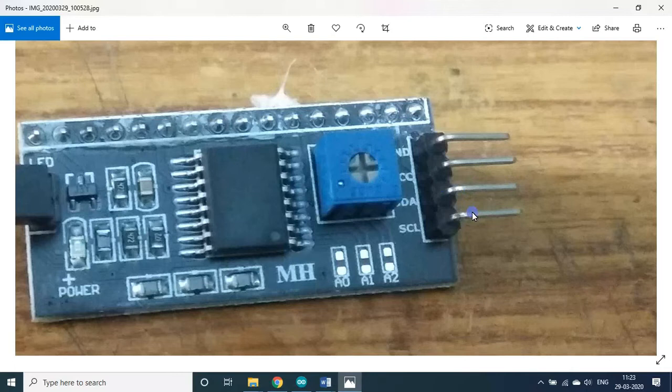So we'll be saving 6 digital inputs. It's a great thing, because digital input and output points are very much essential for the execution of your project. We'll hardly be using all the analog channels, so let us spare the analog channels for the LCD display.